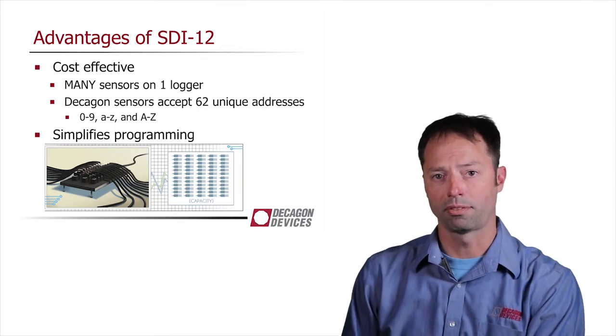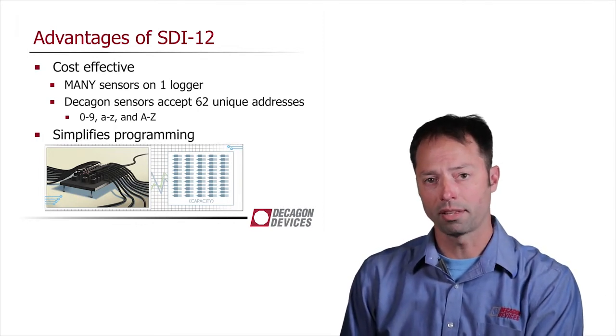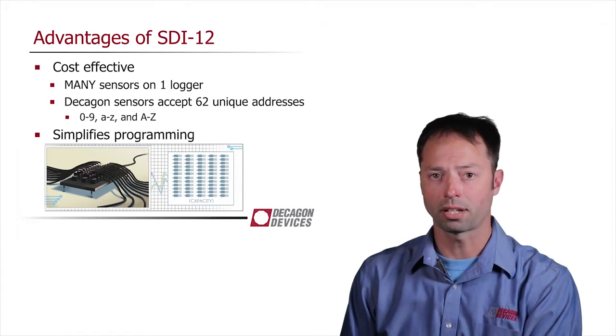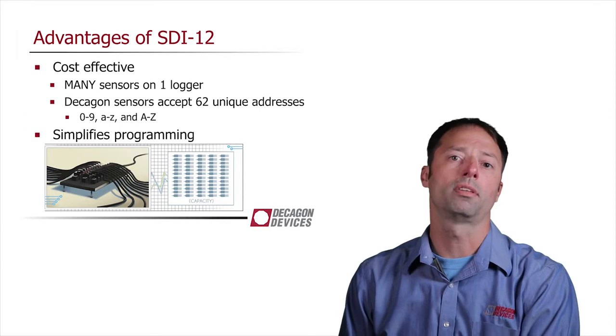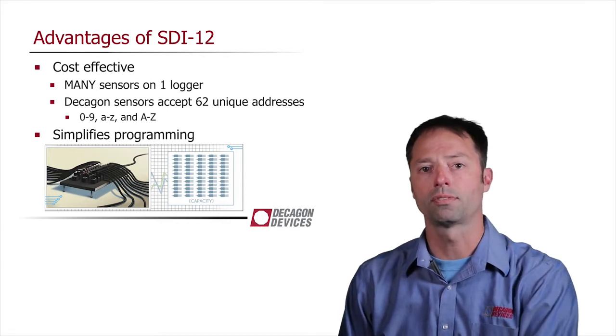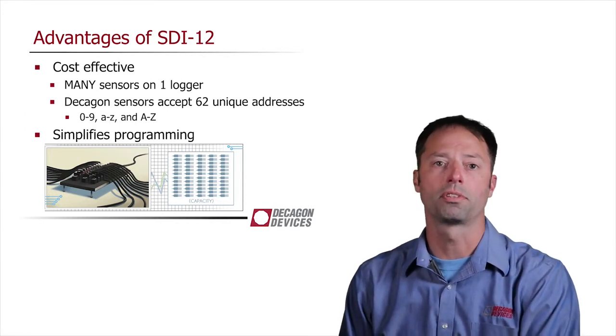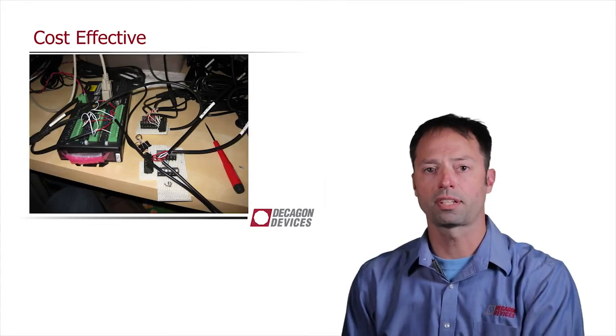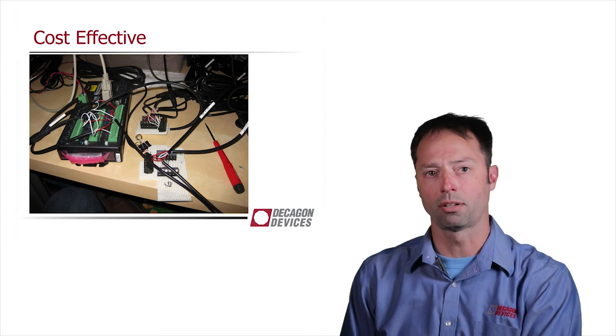SDI-12 also simplifies the programming. The commands in SDI-12 are all standard preset commands, so that it's generally just a few lines of code and you can get the response from the sensor. And they're cost effective because you don't have to invest so much in data loggers.